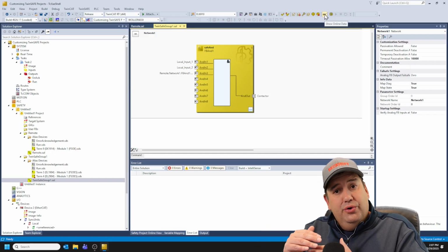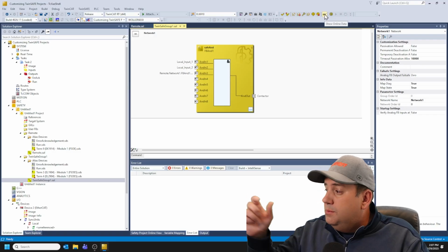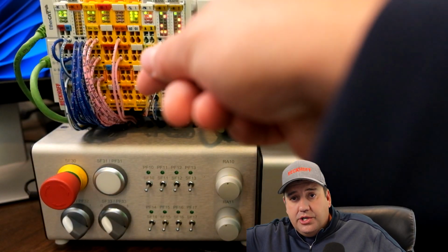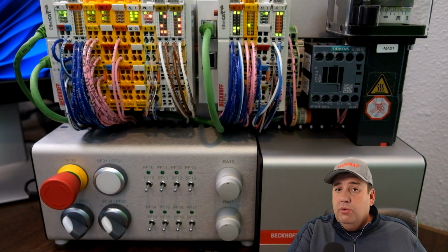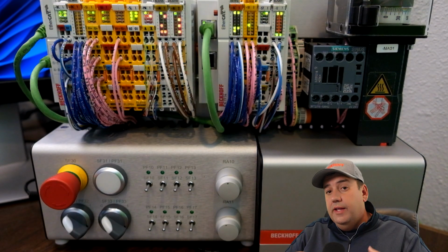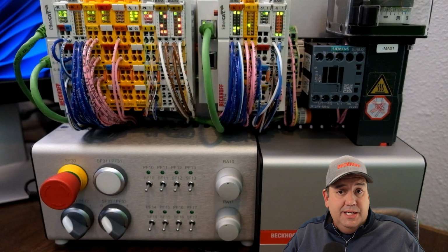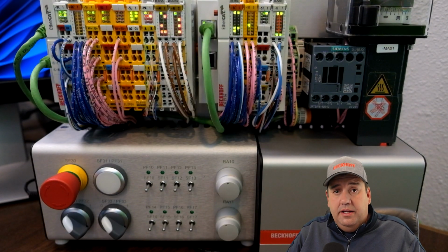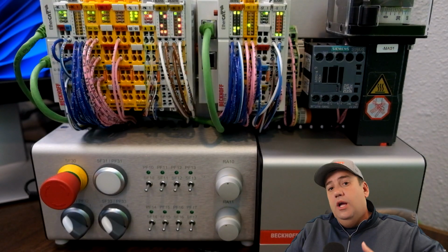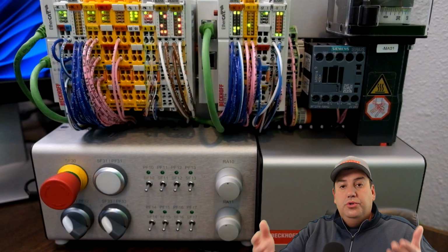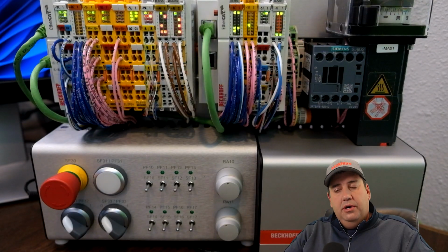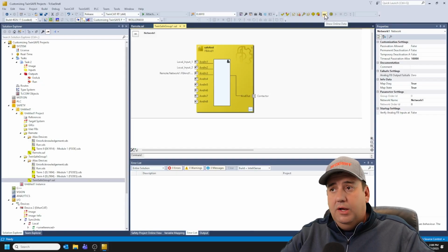And that's because what we're doing is we're passivating the group, and then we're expecting to actually pull a connection within a period of time, because we want that remote hardware to be disconnected so that there's no confusion that it, for an e-stop, for example, is still active and part of the system. Generally, we're going to put our safety system into stop. We'll do the customization, and then we'll put it back into run. So let's see how that works.